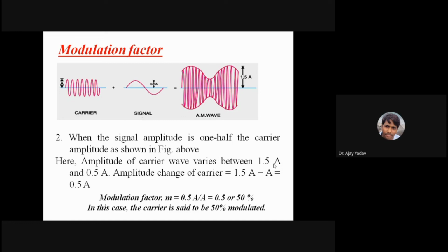So if you see in both the examples, this 50% modulation and the 100% modulation, here there is a variation of the envelope. The amplitude of this envelope changes if you see. And if you see all the interference in the air, try to touch the CRO probes, you will find a signal, not a very strong signal, from your heartbeat or from your body.